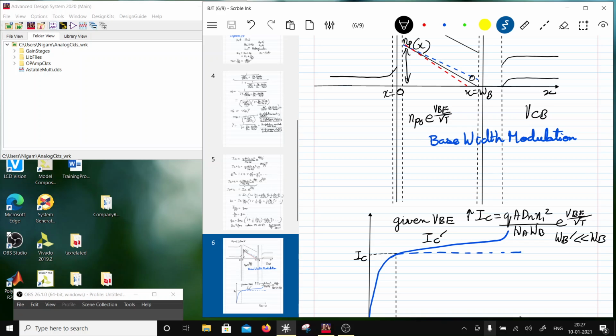if suddenly you want to reverse bias a forward bias diode, what's going to happen? The diode is not going to reverse bias till there are minority carriers in the depletion region. So first you have to drain out the minority carriers from the depletion region before the diode can switch off, right? So minority carriers have to go to zero. So there is a delay of time, and by that delay time the charge has to be swept out of the depletion region.